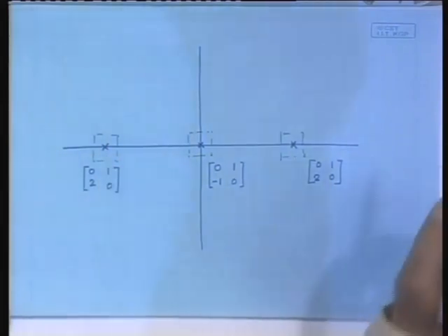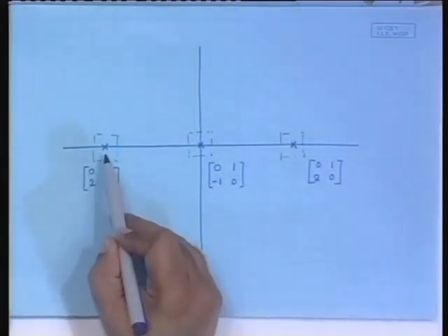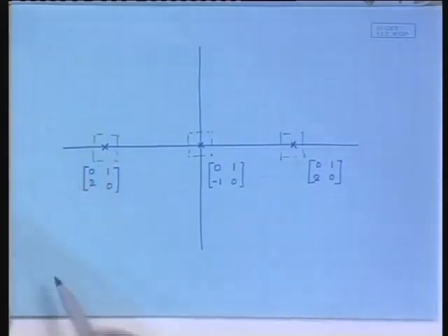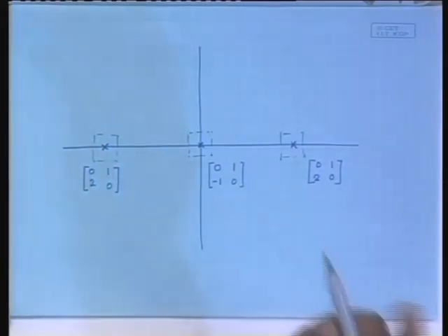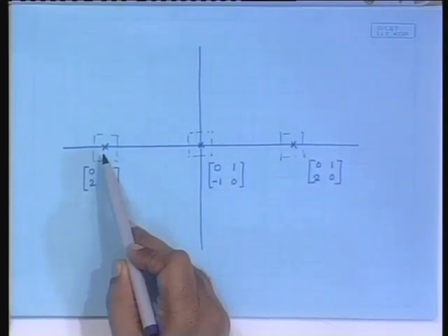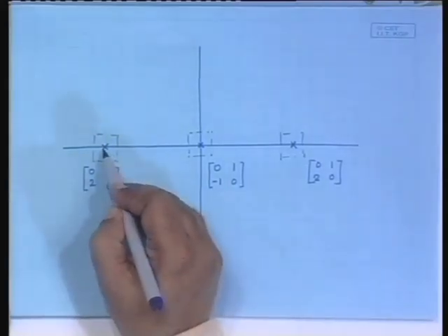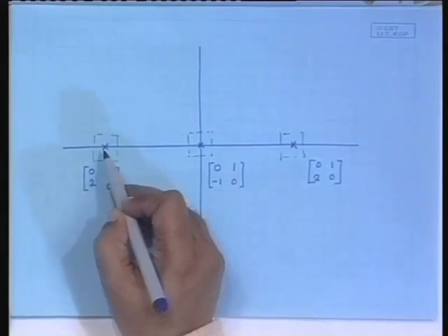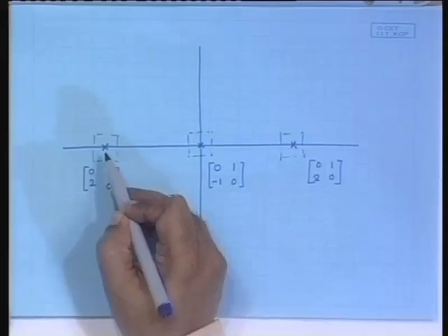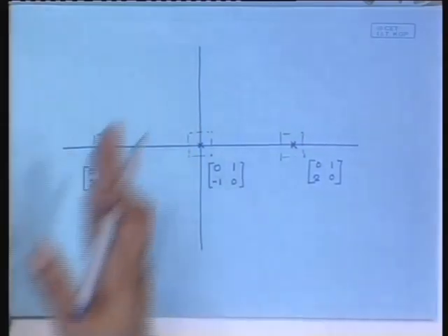Let us start with this particular point where the location is -1, 0. This is the Jacobian matrix. What do you get as the eigenvalues? Come on, it's simple. Plus minus 1. Huh? No. This one cannot be that. Right? Yes. Plus minus root 2 you will get. So, here the eigenvalues are plus minus root 2. Plus minus root 2 means what kind of equilibrium point is it? A saddle.